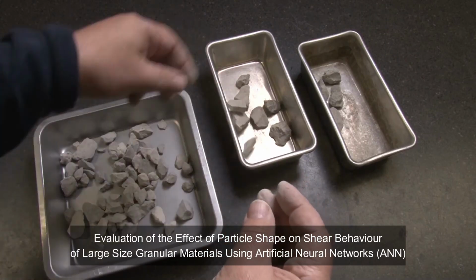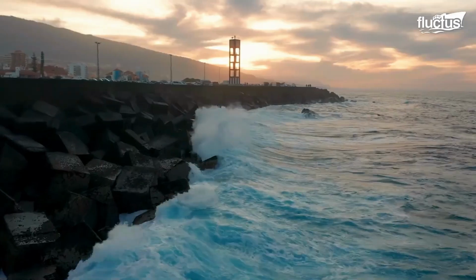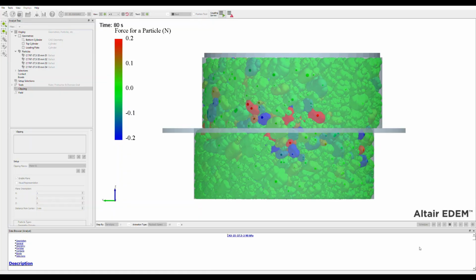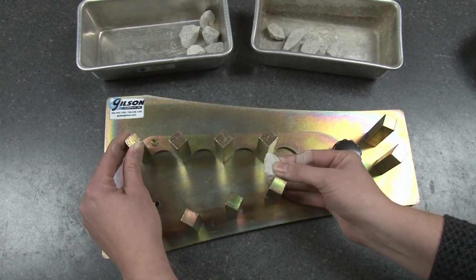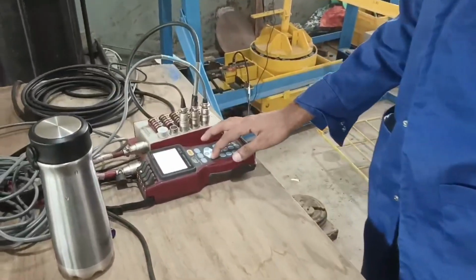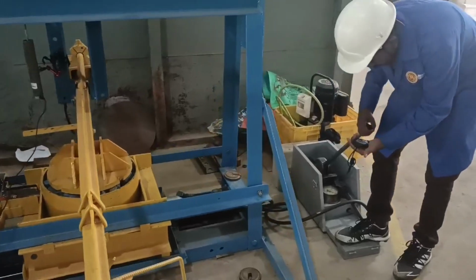The influence of particle shape on the shear strength of large granular materials used in civil engineering, such as breakwater structures and rock-fill dams, is examined in the study. Various particle shapes are simulated using the discrete element method, and numerical values, such as the elongation index, flatness index, and aspect ratio, are analyzed. Additionally, a Python-based artificial neural network model predicts the friction angle and void ratio, capturing the non-linear relationship between particle shape and shear strength.